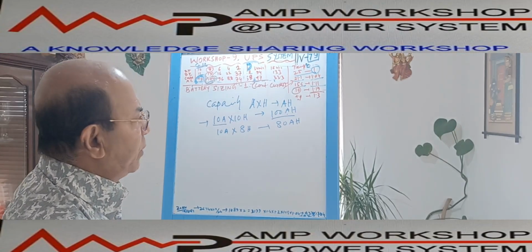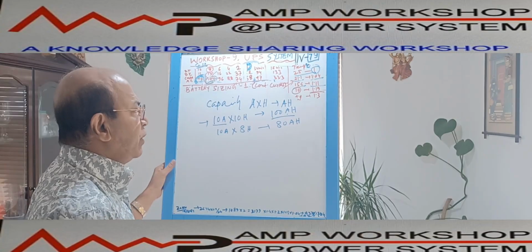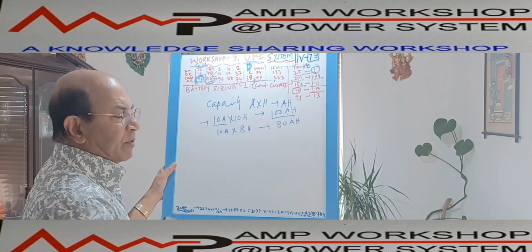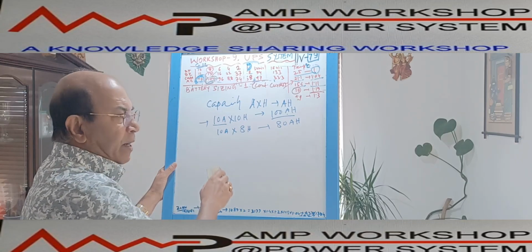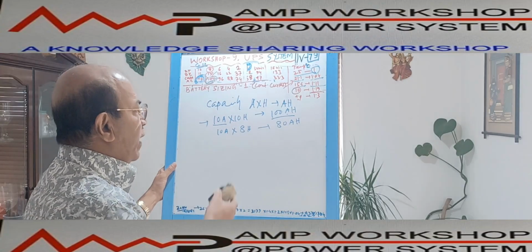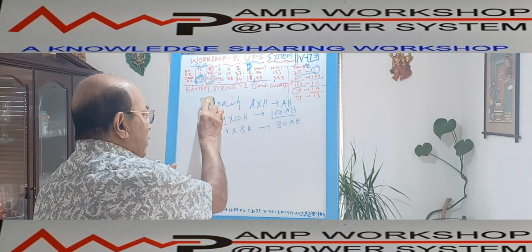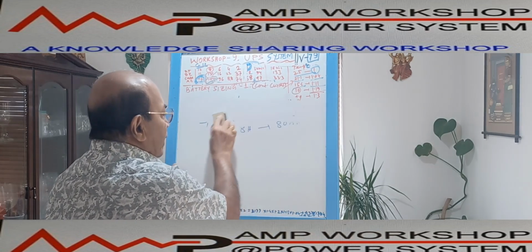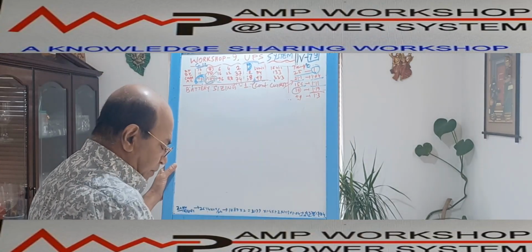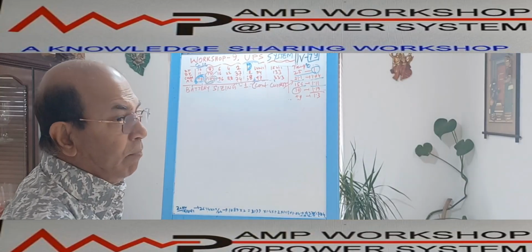Okay. So one of the important parameters we need to know before discussing the battery is the battery capacity. The capacity is measured in terms of ampere hour, meaning how many ampere of current is being delivered and over what period. Multiplying those two factors gives the capacity of the battery. That is the first parameter. Then a couple of parameters are required after this, and those parameters are related to the voltage.